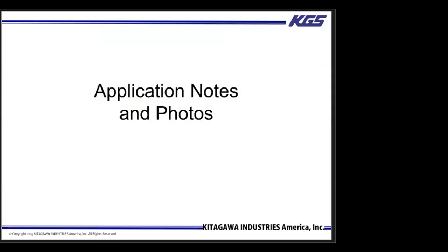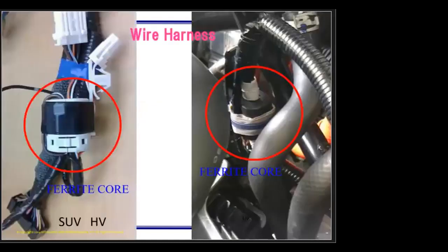And now next, we will discuss the current application notes and how ferrite is used to solve possible interference issues affecting the radio and issues caused by the battery voltage monitor unit. So these wire harnesses use high frequency ferrite core to filter out any outside noise from entering into the harness and affecting the FM radio band. These are used for immunity.